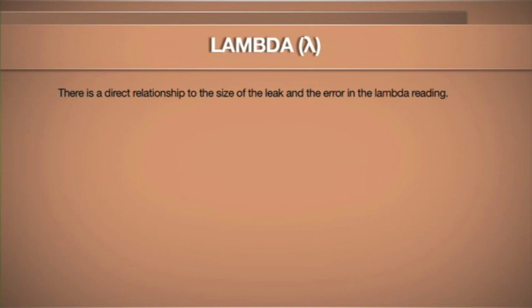So for an example, if I had an exhaust leak in a vehicle and the exhaust leak was about 10% leakage, the reading that would be taken from the gas analyzer would be plus 0.1 lambda, or approximately 10%. The effect would be an incorrect diagnosis.